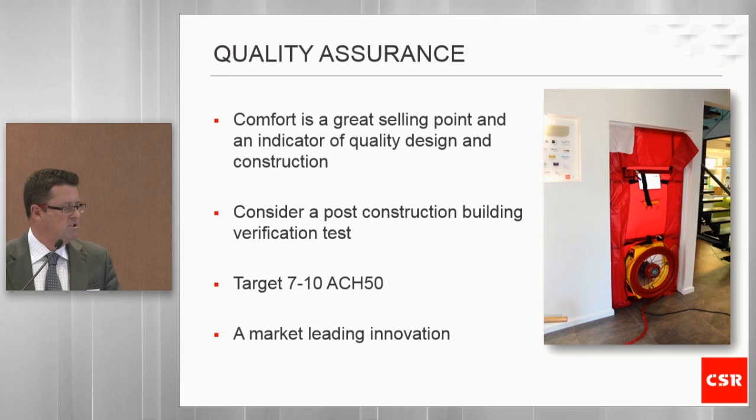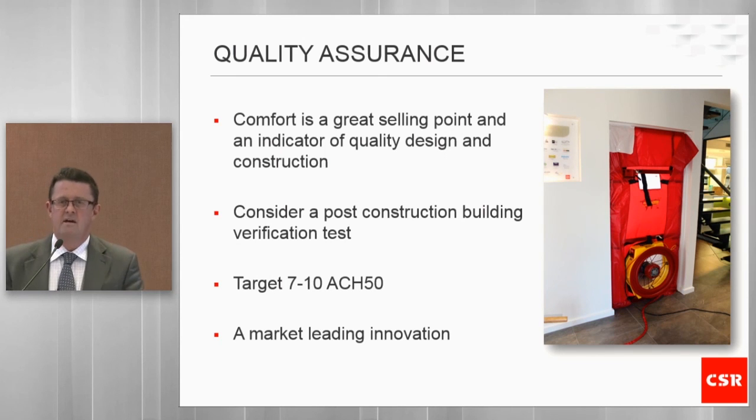Consider a post-construction building test using the fan blower test. These sorts of tests are only about $500 to undertake. They're not very expensive. And what you may find is that you don't get the total improvement in the first house. You do some testing, you may not get the absolute perfect result from day one, but it allows you to put in place some measures as you move forward to continually improve and test it again.